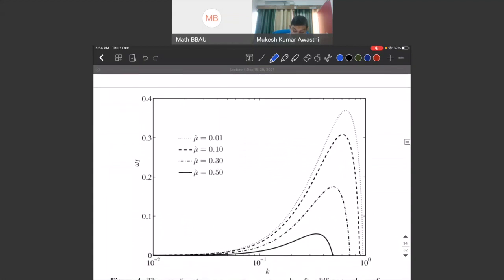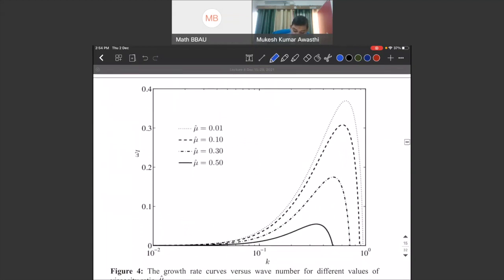Now here we have studied the effect of viscosity ratio. Viscosity ratio, we know that mu cap is mu1 by mu2. Mu1 is the vapor viscosity, mu2 is the liquid viscosity. So if vapor viscosity increases, flow will be impeded, and then the perturbation growth will be slow. But when the viscosity of the upper fluid increases, definitely it will create more energy in terms of viscous dissipation, and that will enhance the amplitude of perturbations. Hence, vapor viscosity has stabilizing effect, and water viscosity has destabilizing effect.